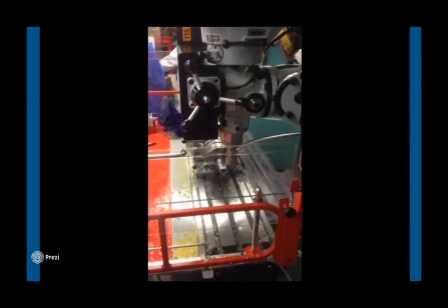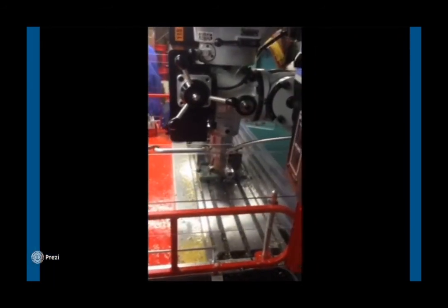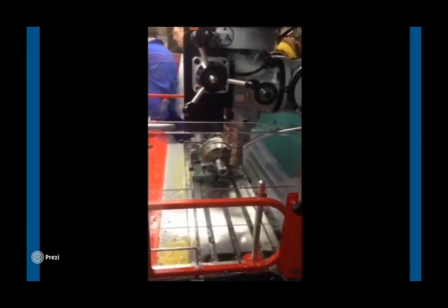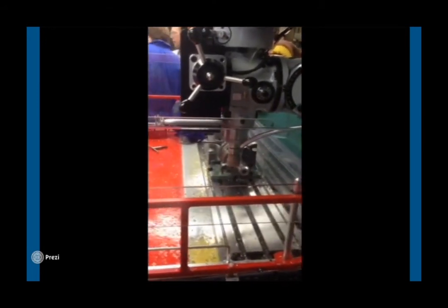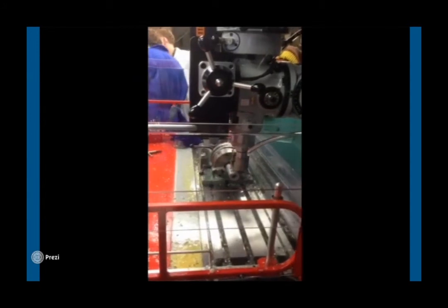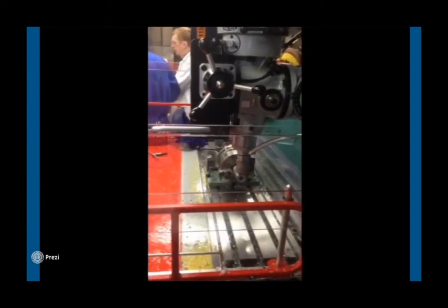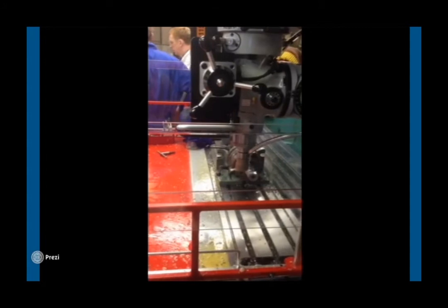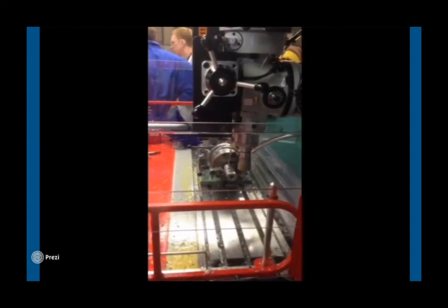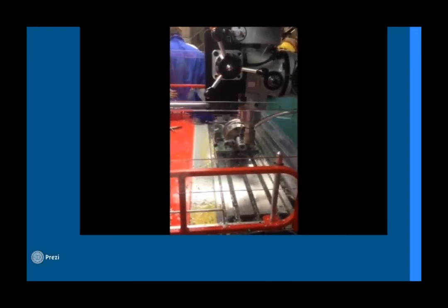The cylindrical block is then put through a milling machine and cut to the desired shape. The milling process is used to produce prismatic surfaces that the harp design encompasses, and is effective as it works based on the 3 orthogonal axes, disregarding the cylindrical surface. For the same reason, the milling machine is used to drill the holes required by the design on all 6